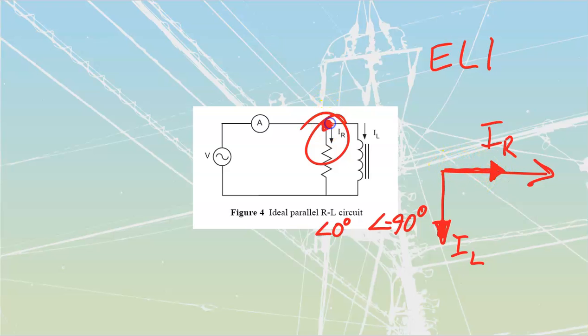These two currents are going to enter this node. One of them is going to be in phase. The other one's going to be 90 degrees out of phase. Together, they're going to sum up to become a vector sum, where they're going through the main part of the circuit. Then they're going to split into their individual components, 0 degree and negative 90, and then they're going to recombine over here to go back to our source as that vector sum that we will have.